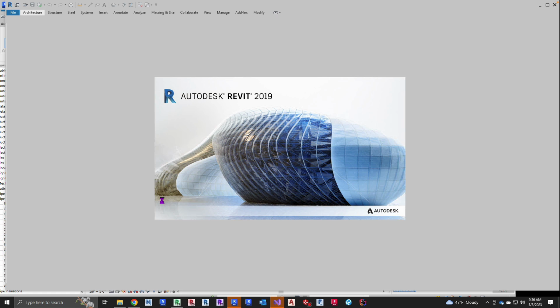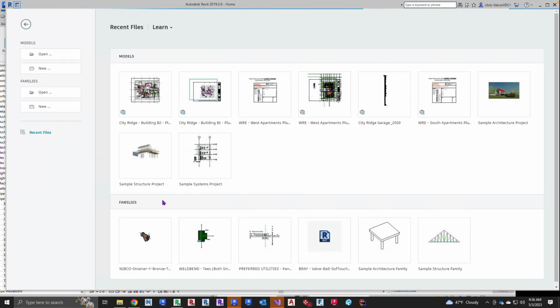So earlier you were saying, I think it was like 2013, you said there was a change with the lookup tables. Yes, in 2013. Prior to that, you had to ship it like this. This file is from 2012. When you created your Revit file, you had to create two files. You created your Revit extrusions, and then you created a text document that you would link into it. Right. As of 2013, they embedded the lookup tables into the files.